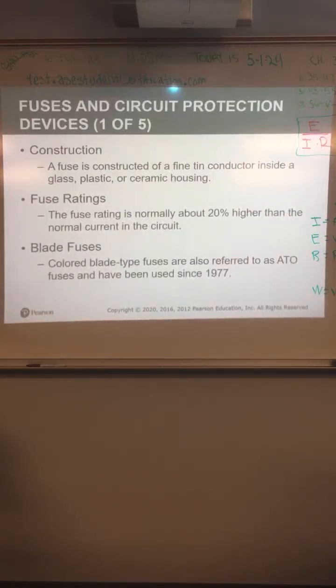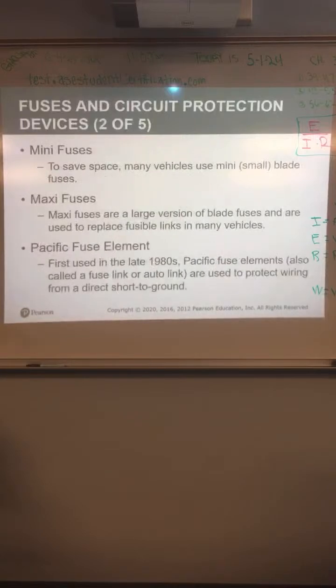Color bladed fuses, also referred to as ATO, have been used since '77. There's obviously different sizes. You can see some of them in that fuse panel there. Mini fuses, maxi fuses, and the PFE Pacific Element fuse. Used to protect wire from a direct short to ground.